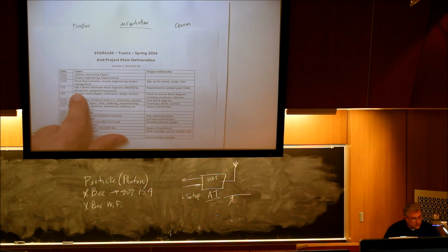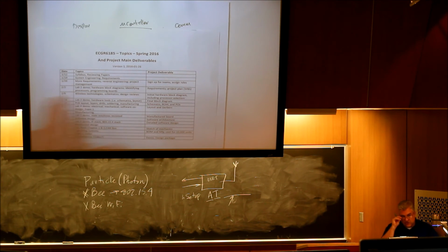I did not really put great effort into identifying processors, but previously we talked about the benefits of the MSP430 especially. Low power. Very low power, right? As opposed to the Renesas, even though they claim low power, we've been using a lot of the higher power devices with the RX63N. ARM, is that a low power device? Yeah, not all that much. Arduino, is that low power? Yeah, not quite. What about Raspberry Pi? No, all right?